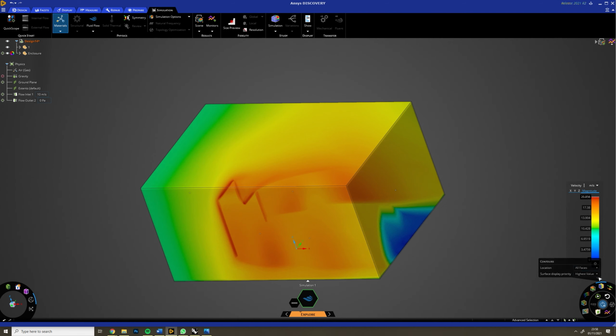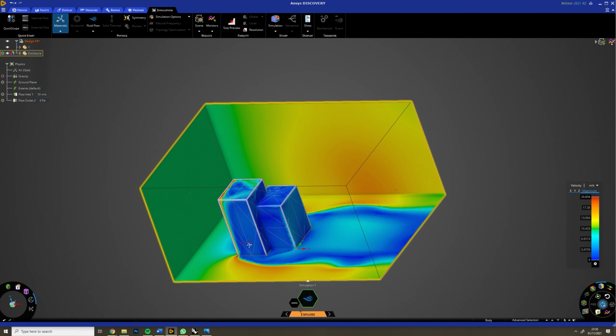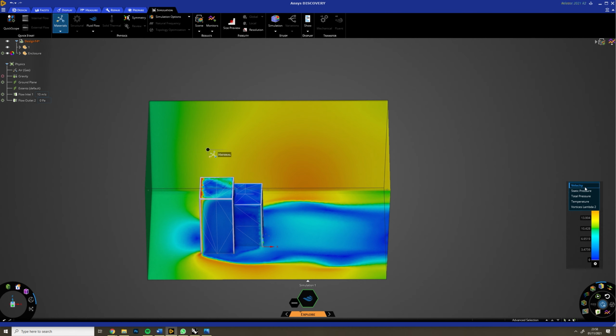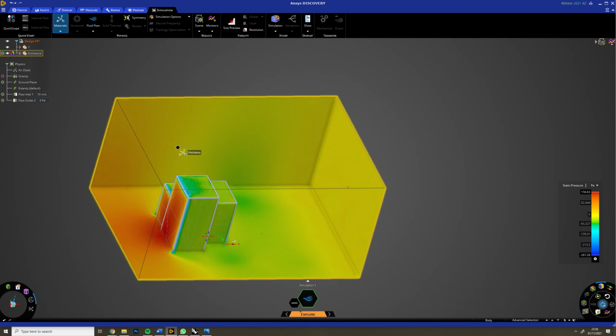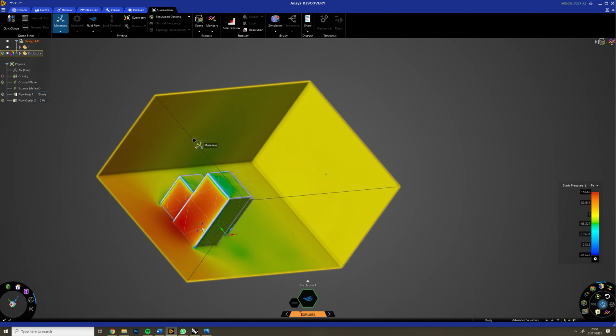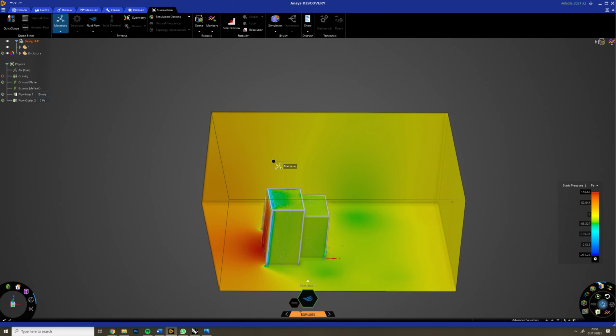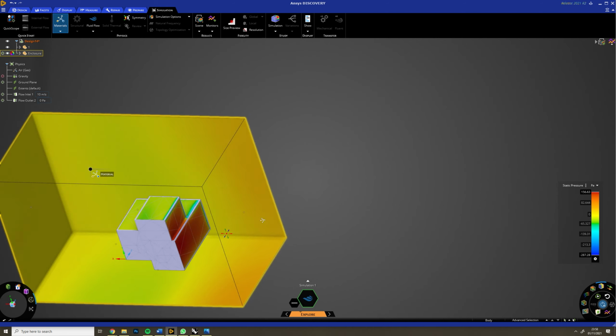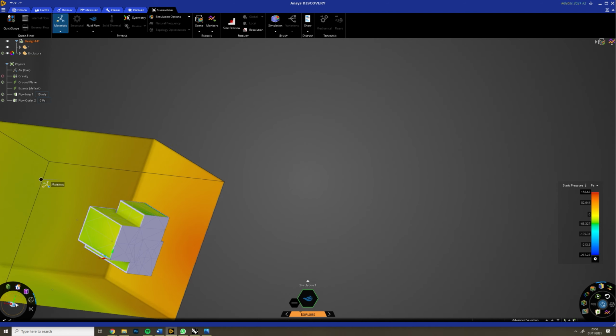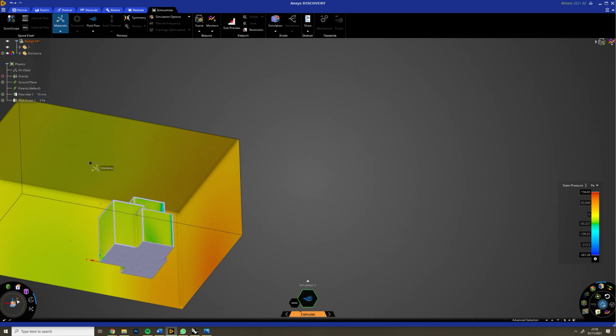And we can also check the pressure on the faces. So we click on the contours, click on the inner, and from over here we want to change from velocity to static pressure. Now we can see which areas or which faces receive quite high pressure from the winds. And if you get stuck rotating until you get upside down, you can also use this cube to rotate yourself around to get out of tricky situations.